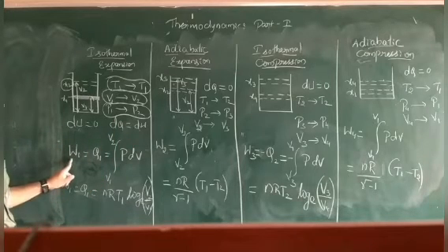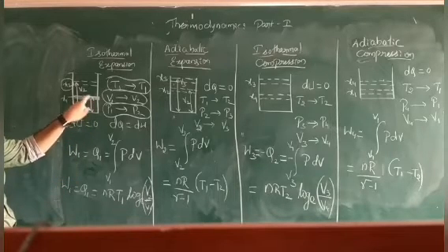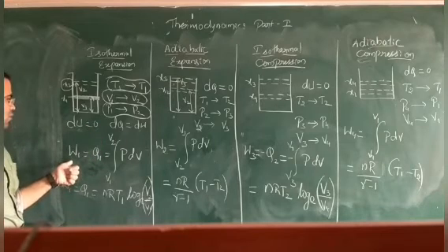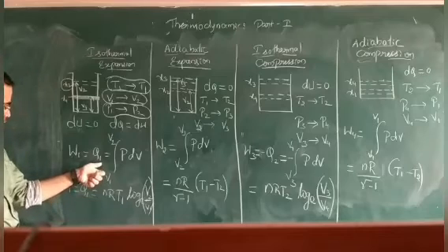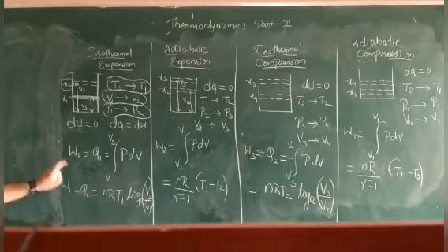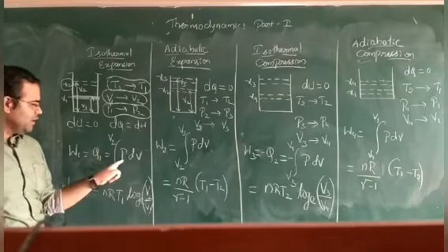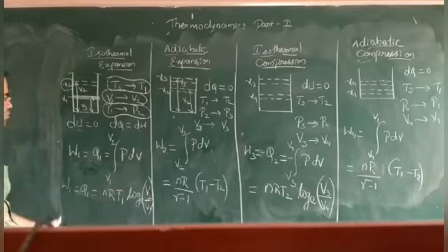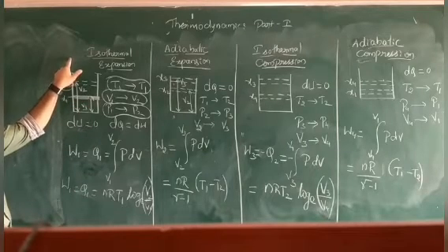Now we will identify the total amount of work done, changing from a volume of V1 to V2. How much work is obtained from the heat energy provided, we substitute into the equation. So you are integrating from V1 to V2. The small amount of work done is P dV. When we simplify, we get the work done in the isothermal process, which we discussed in the previous content.